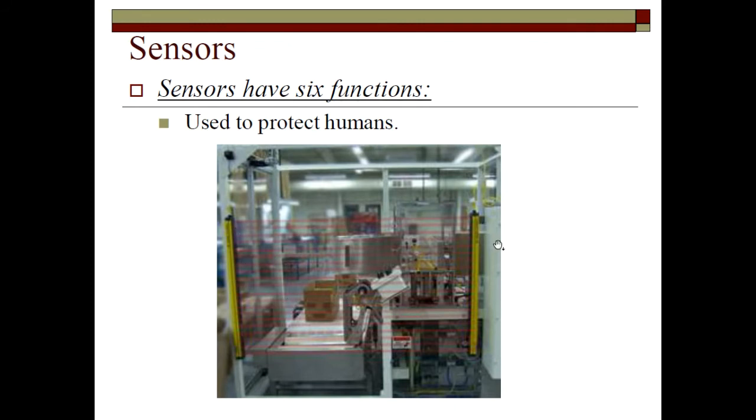So all these light beams are sending out and triggering a sensor and saying yes, yes, yes, yes, yes. And then if you break that beam, one or more of these are going to report a no and send out a 0. And then that's what the robot senses to say, hey, I'm missing input. That sounds like an error, and I'm stopping and I'm turning on the stop. Okay, so that would be a normally closed.